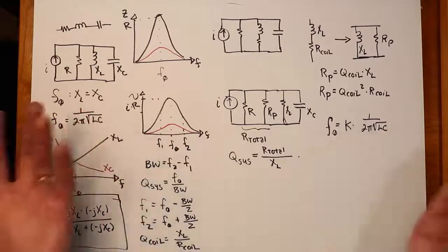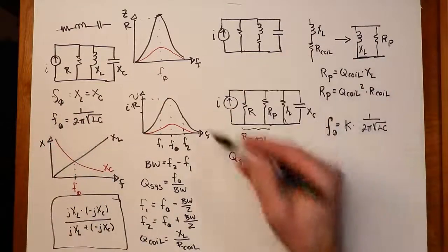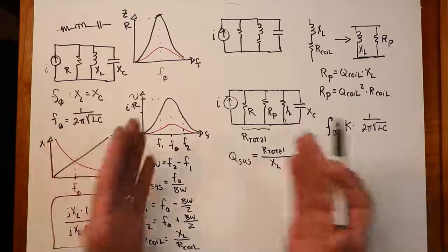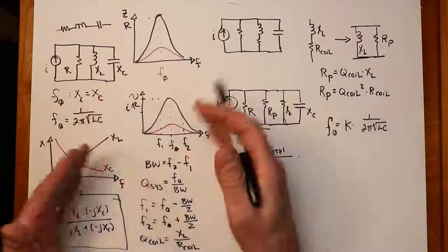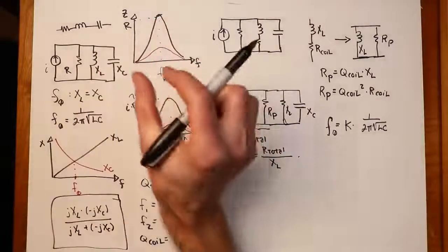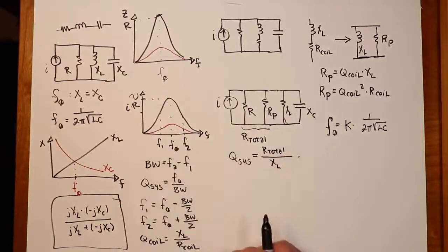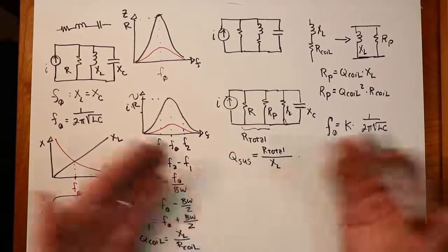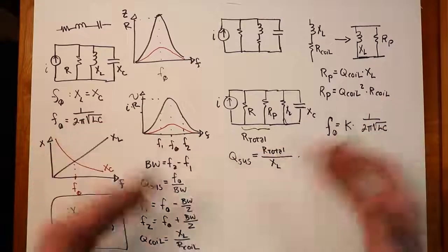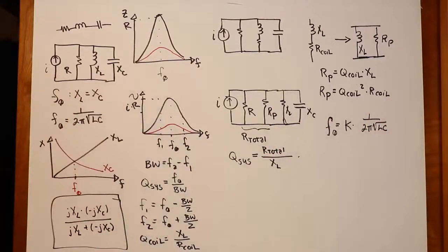To be honest with you, no, it's not usually a huge problem, because the whole reason we use tuned circuits is to get the selectivity. In other words, we don't really want broad Qs. The whole point is to sharpen these things up so that there is a narrow range of frequency, whatever the bandwidth here is that we need. So I don't really normally want a circuit with a Q of 2 or 3. I'm looking for much, much higher values, double-digit values. That's typically what we're looking for.